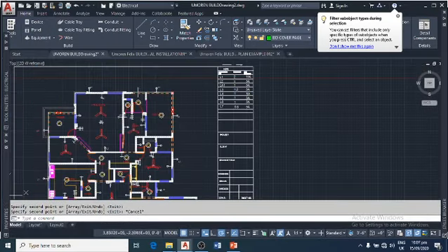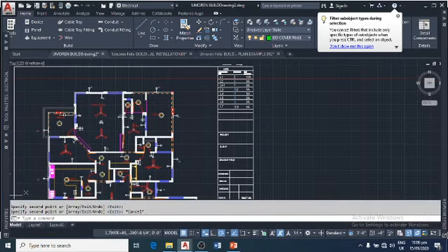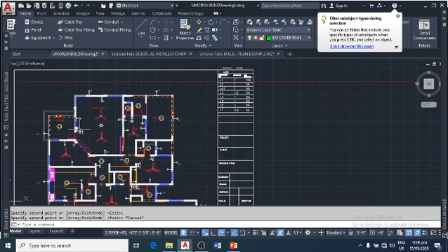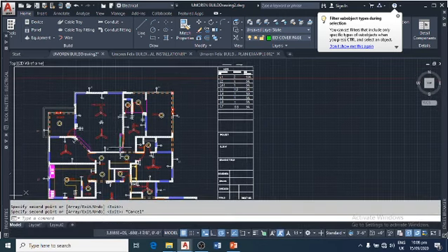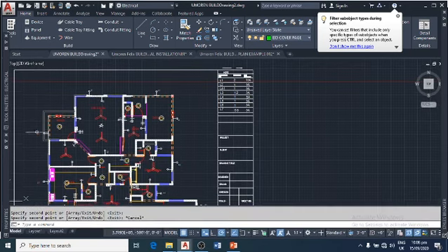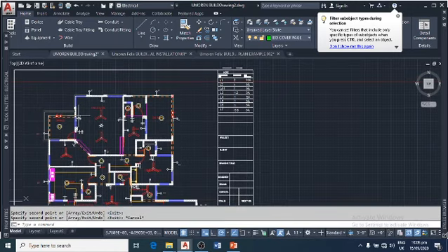So let's assume 16 points of our electrical components, 16 luminaries here for the security points, and each of them is using 20-watt lighting. If each is using 20 watts, it will become 20 times 16, which is about 320 watts.